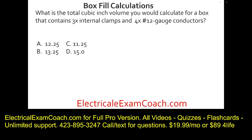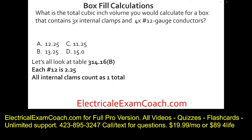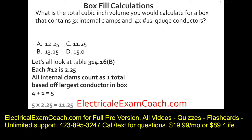What is the total cubic inch volume you would calculate for a box that contains 3 internal clamps and 4 12-gauge conductors? We head to our table. We know what each 12 is. All internal clamps count as one total based off the largest conductor in the box. We only have one size wire in the box, so we're good to go. We take our 4 original conductors plus our 1 clamp count, and that equals 5. We bear our math out, and we select C.